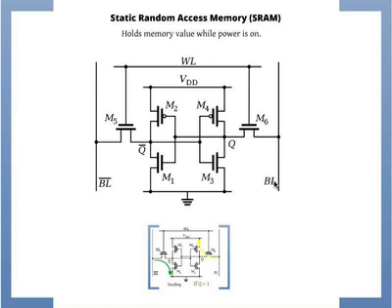So now my bit line will very quickly go up to VDD, and I can detect that. But more robustly, if you follow the same logic, you will see this bit line bar will actually go to ground. It's easy to see because M5 is on and M1 is on, so this circuit is closed.